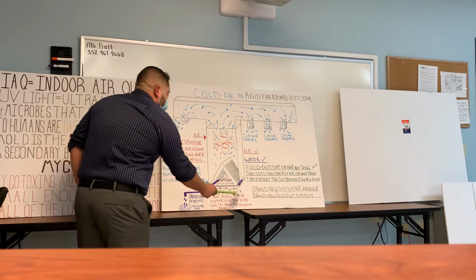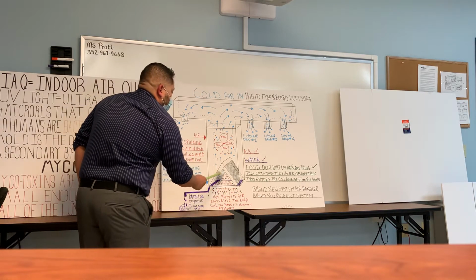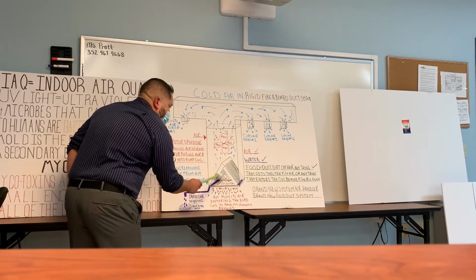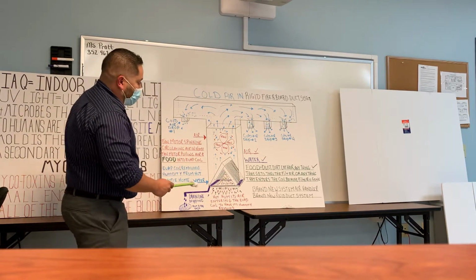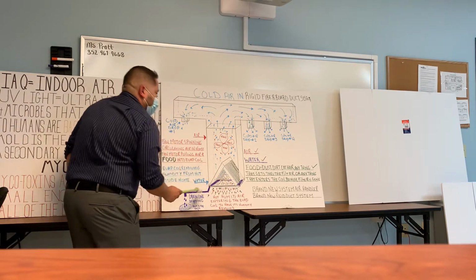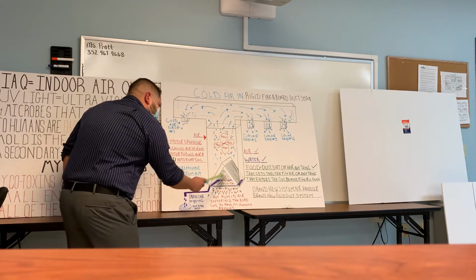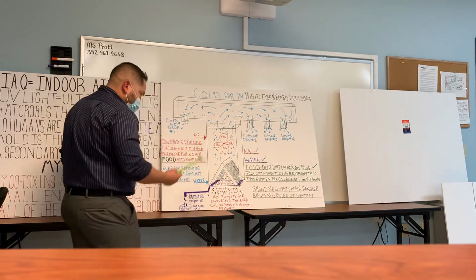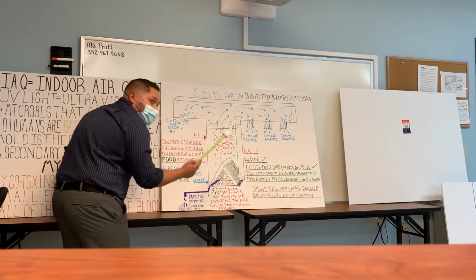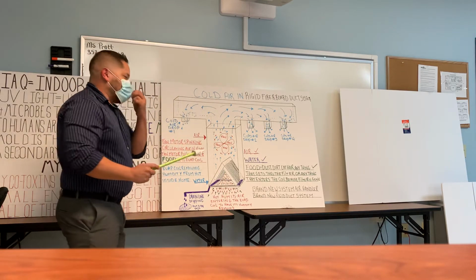You have hot, humid air entering the evaporator coil to have its humidity removed. It's bringing food particles into the coil. Now, what you'll notice about this coil is it's a thick coil. It's not thin. It's almost like the radiator of a car. It's got the underside of the coil and then the top side. Air comes up through the bottom and it makes contact initially with the bottom side of the coil. This is where the magic happens.